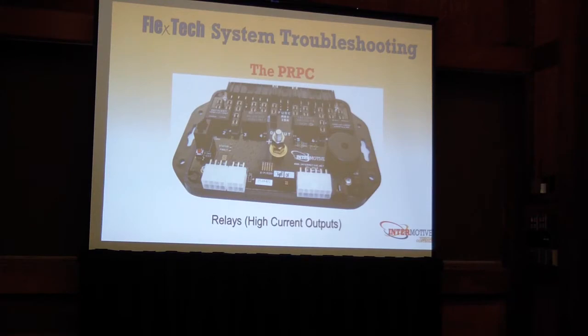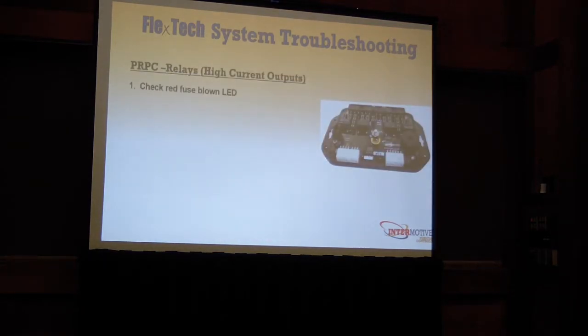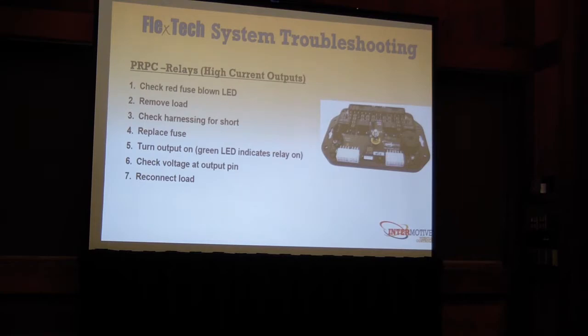Once you verify that the hardware is still functional, you're seeing 12 volts all the way out to the output pin, fix your harnessing, check for shorts out there, fix all that, reconnect it, and you should be good to go. So there's just a summary of what I just talked about.